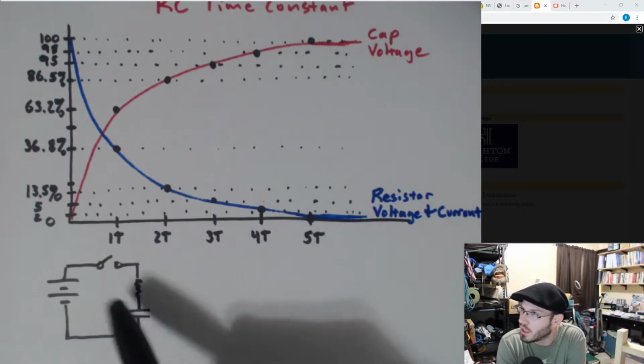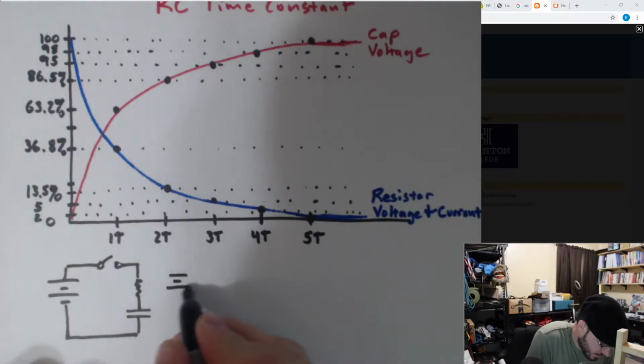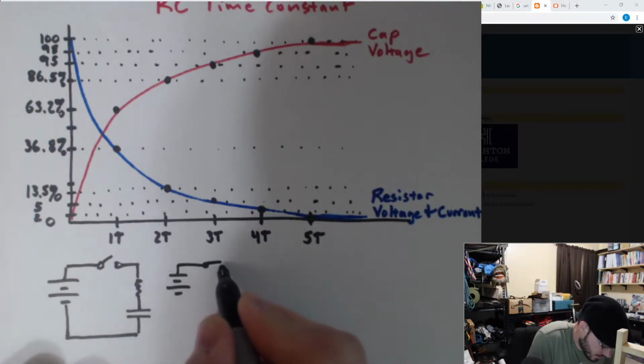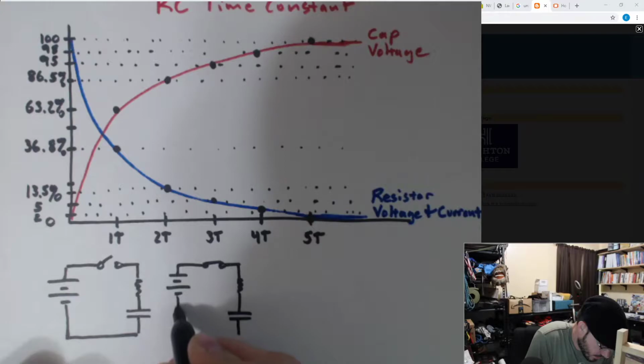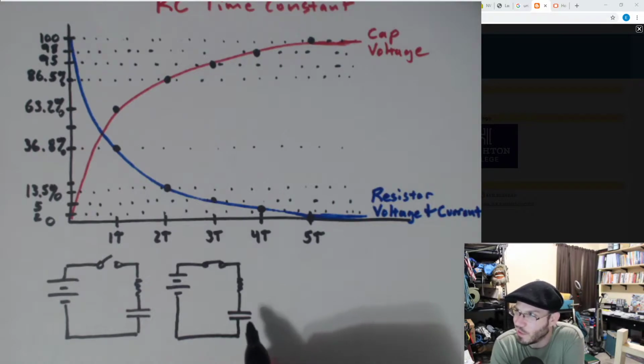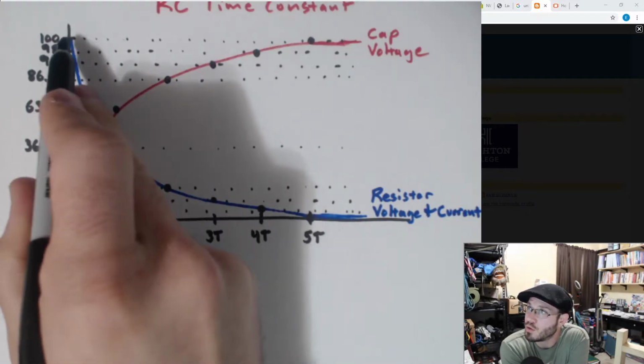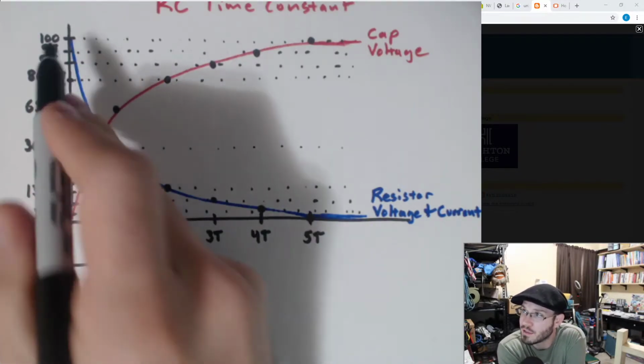Hence, we have no voltage on it, we have 0 current flowing through it, etc. However, at time 0, when we close that switch, that capacitor, when it has 0 charge developed on its plates, will behave like a short circuit for that brief moment in time. Hence, we would actually get the most current going through the circuit as possible.